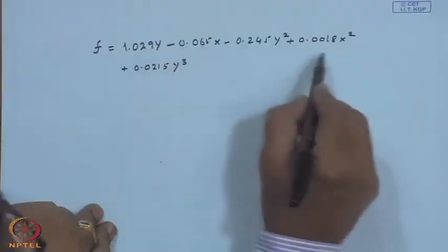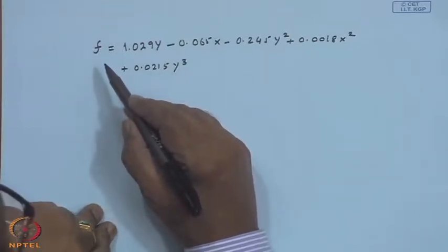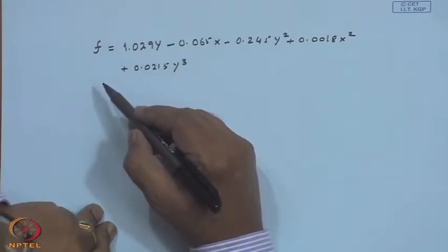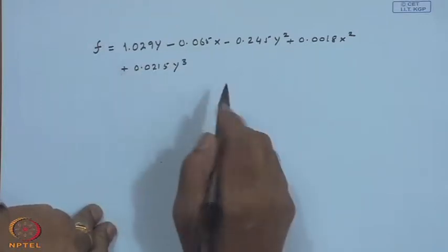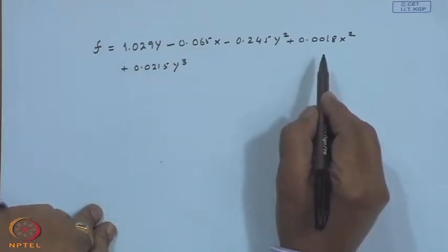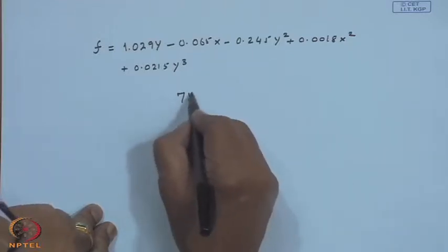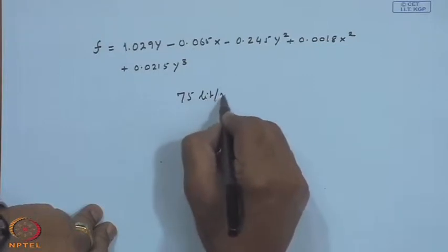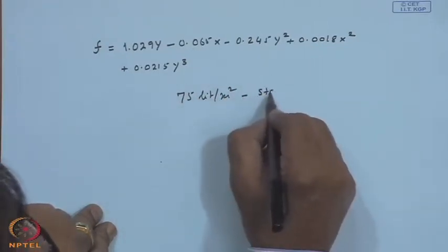However, the slight difference between the air and liquid based systems comes mainly from the storage and the heat exchanger effect. In addition, you will find that the liquid based systems have a certain volume of water, like 75 liters per square meter of collector area, as the standard storage.